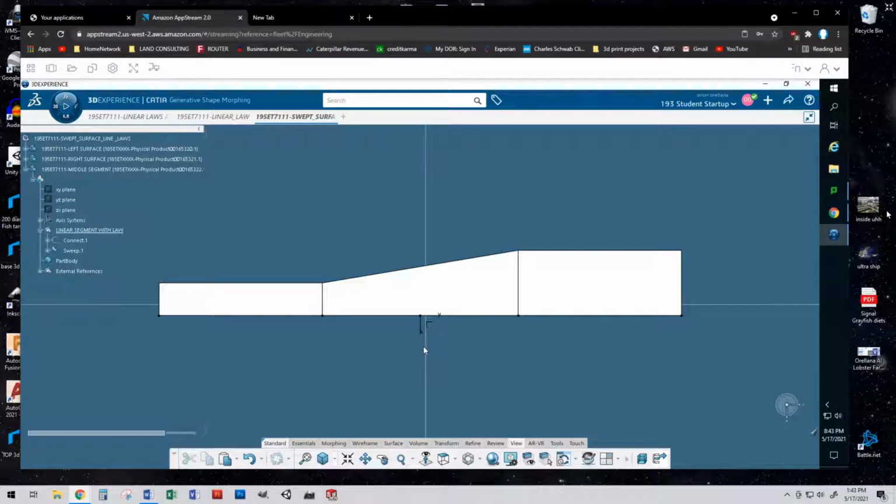Anybody can do these CAD models. Understanding left buttock line, right buttock line only applies to aerospace, correct? No. False. Where else is it used? Automotive may use it. Well, who else might be using it? Shipbuilding. In fact, it came from shipbuilding. Those coordinates aren't aircraft coordinates because it got water line in it. But aircraft decided to use the same coordinates as shipbuilders. So that's where that comes from, and you guys need to be familiar with those terms, okay?